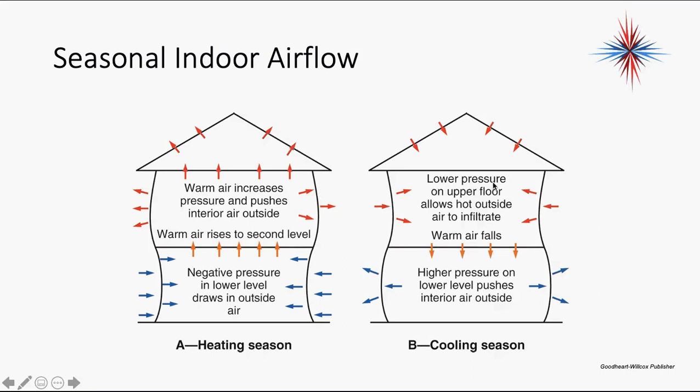So, where we left off with this diagram of the weird shaped houses. We were talking about how, during heating and cooling, the pressures are a little bit different because of the stack effect, as it's called, of the airflow. Cool air falls, hot air rises. So during the heating season, in the winter months, we're pulling cold air in through any crack or crevice at the bottom of the building. It's going to rise and attempt to push out at the top. So stack effect is the word that's going on here.